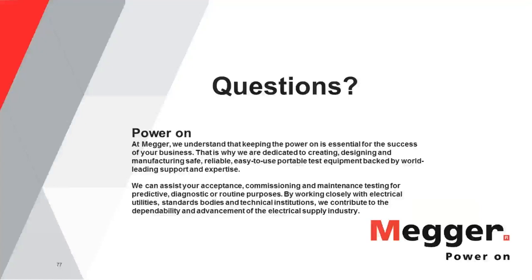That's good. What I can tell you is you might try organizations like IEEE and NETA and so forth, because they try to do things of that nature. One example I can think of is the IEEE motor testing or rotational equipment testing standard, number 43, which I think gets mentioned further down in the questions. That was revamped around the turn of the century, around 2000.